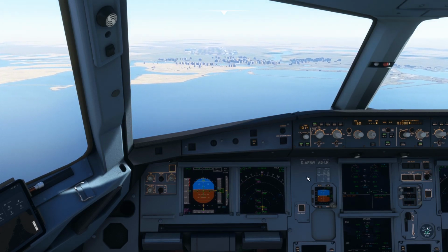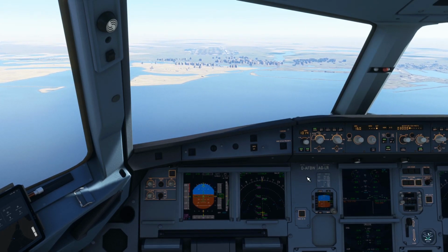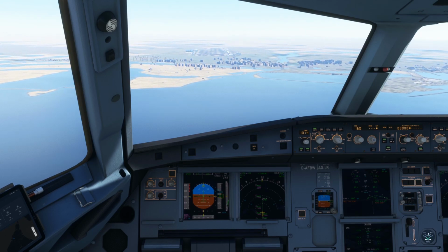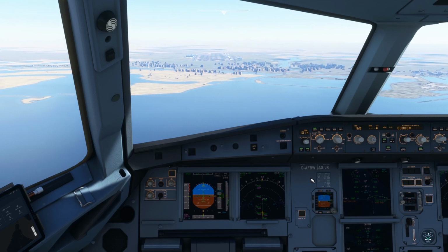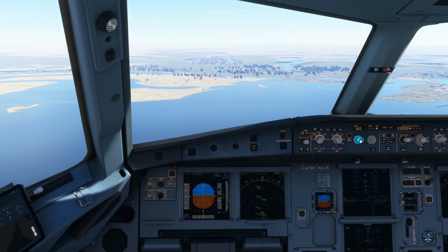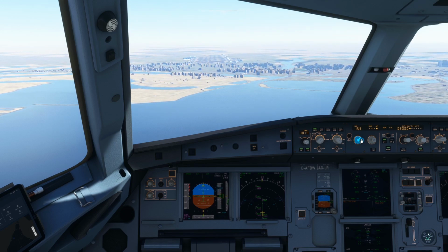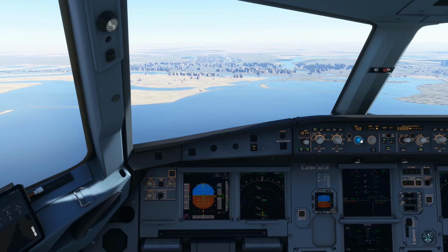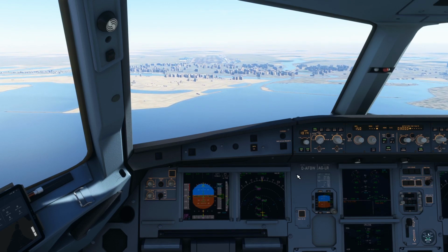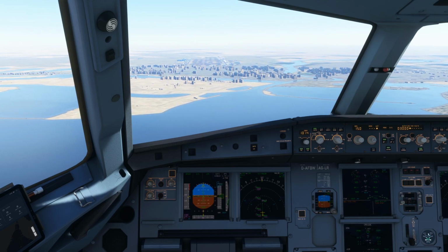It means the plane is not only trying to catch, but rather it's following the glide slope. And eventually at a certain point, we will touch the runway at a nice point, 150. I'm further reducing the speed. Below 2,000 feet, I will get the gears. Or let's get the gears at 2,500. Okay, it's time to lower the gears.